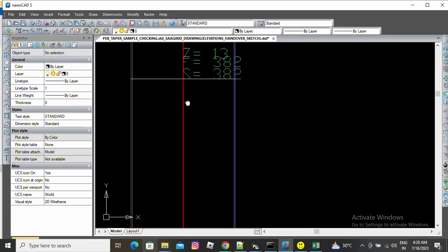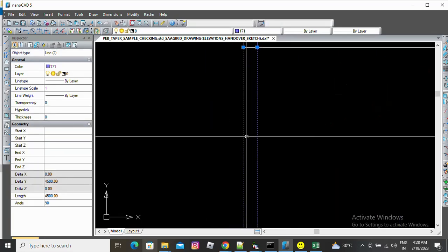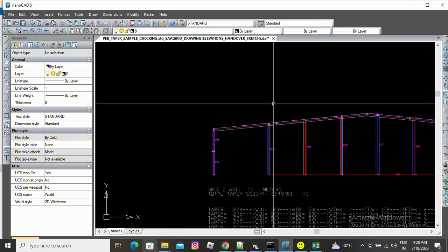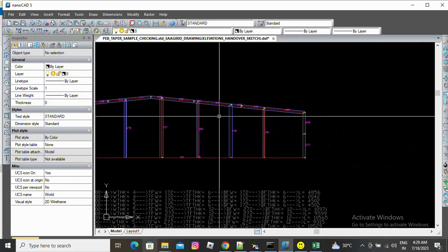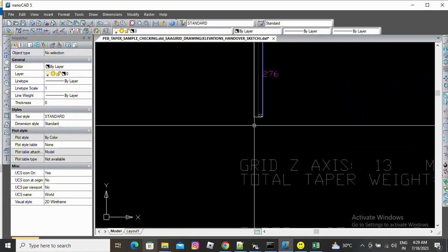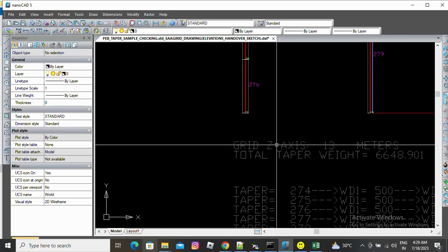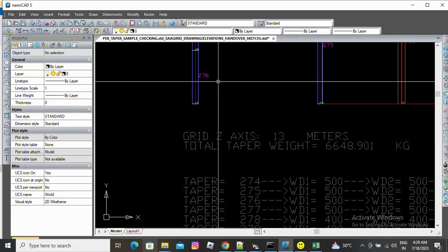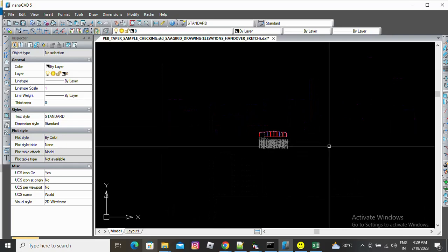Here we can show you the web. The flanges are all properly calculated in thickness. The webs are also properly calculated. If there are tapers, then on one side, the outside, it is aligned properly. Its nodes are also represented here in small green color. The start is this with the Z value of 13, and Z value here is not the structural engineering Z. This is the Z axis coordinate, that is 13 millimeter. At the 13th millimeter, Z is shown here.